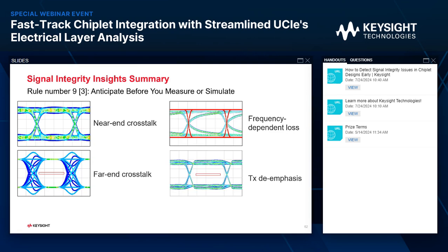We also learned that increasing spacing is great to reduce coupling, reduces channel length, reduces loss, and most importantly, hey, it is best to find the root cause to fix the problem.